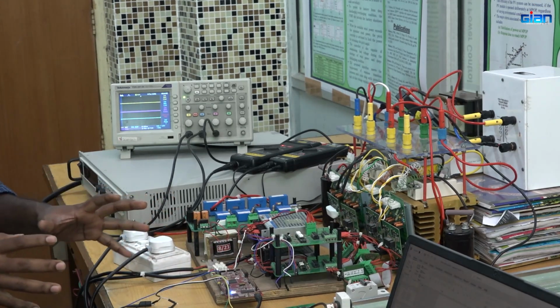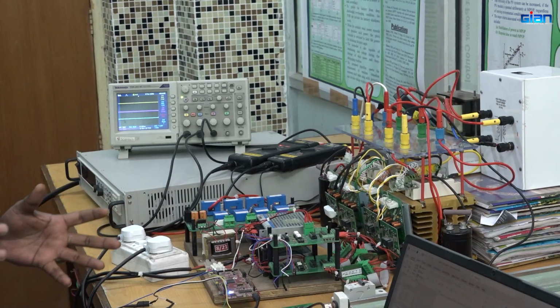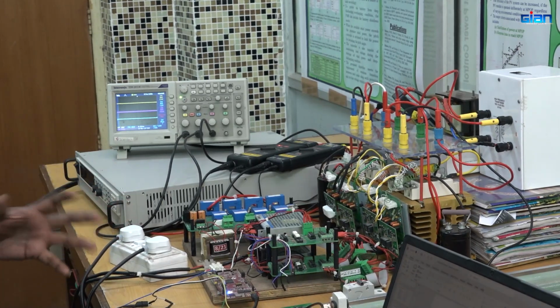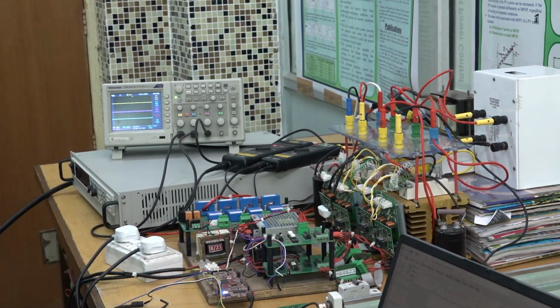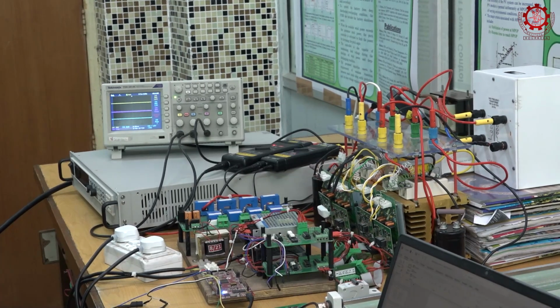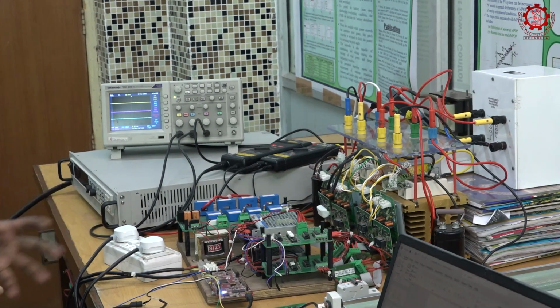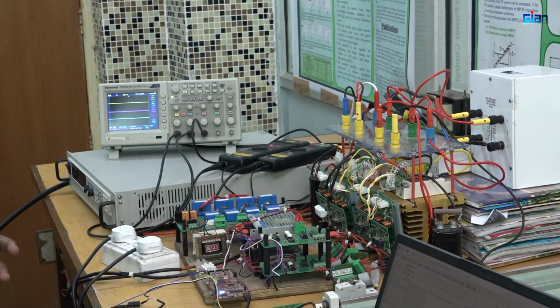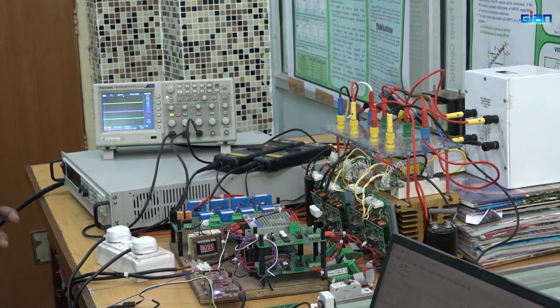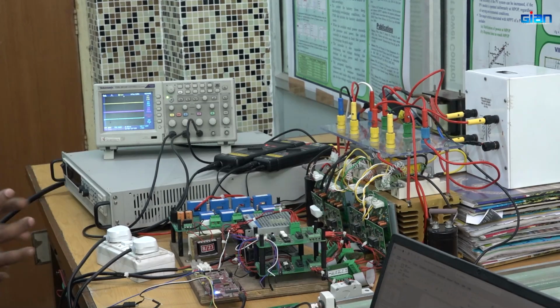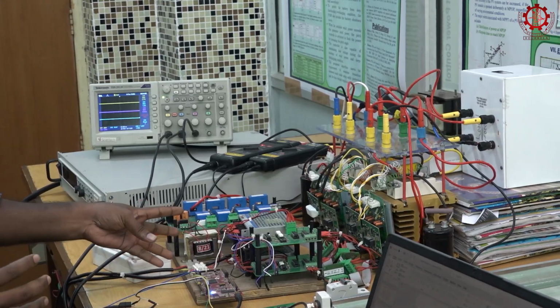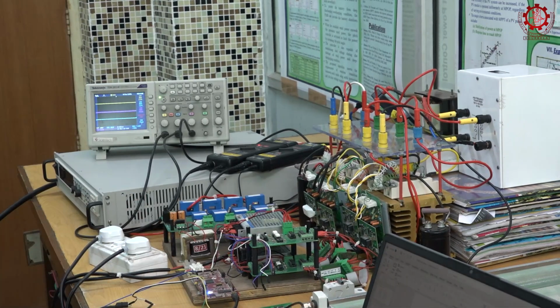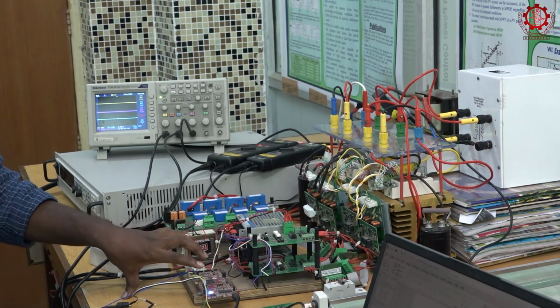These are multiplexed, so we can use them as PWM ports and also as ADC and DAC ports by giving a proper input signal. It has a 12-bit mode for ADC signals. The ADC converts continuous signals into discrete, digital signals. And we have 3 DAC modules also.